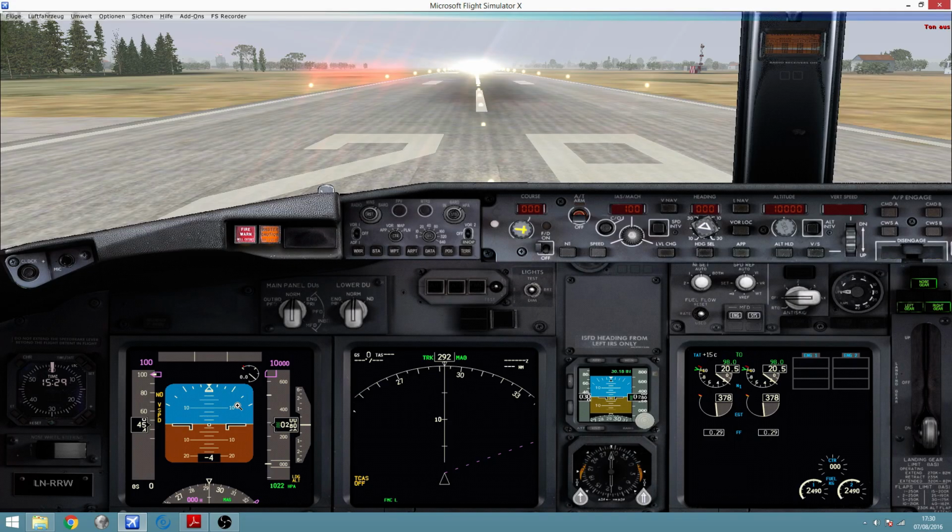I won't enter into details because this is something we've supposedly seen in class on the blackboard, and you should have done some exercises. So please be aware that when you come to the lab, you are able to compute the transition level given the value of the QNH and assuming a decay of 1 millibar every 30 feet. Good.